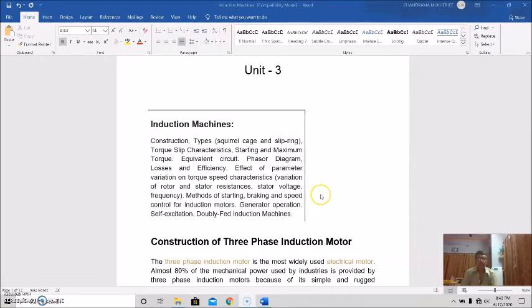And we also saw how three windings spaced 120 degrees apart and supplied with balanced alternating current produce three pulsating MMFs, and when they are added up, the resultant MMF is rotating with a constant magnitude and at synchronous speed in the air gap.